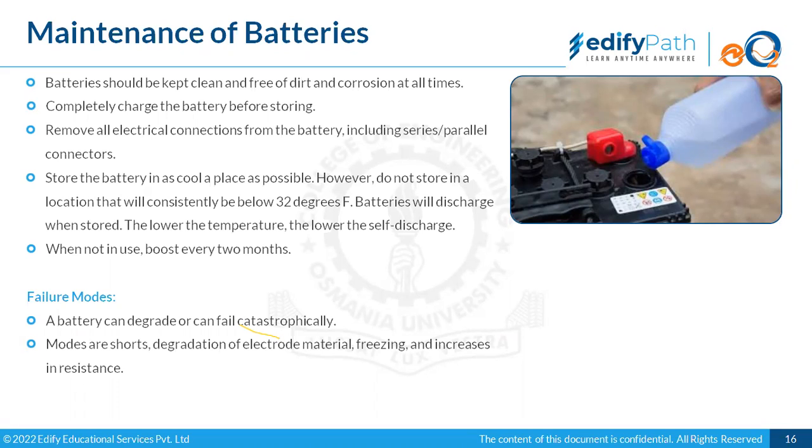Store the battery in as cool a place as possible. However, do not store in a location that will consistently be below 32 degrees Fahrenheit. Batteries will discharge when stored.